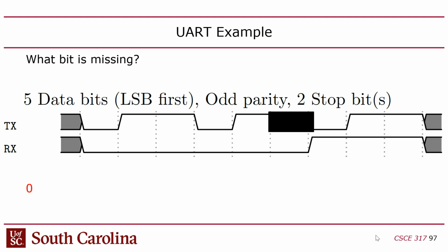Yeah, I always find that confusing too. The parity bit is not intended to be a signal in and of itself telling you whether it's even or odd. It's meant to pad out the bits to make the total number of 1 bits even or odd, right? It's meant to correct the number of 1 bits. But if you think of it as a separate flag, then you could just reverse the logic and say that odd parity is 1 when there's an even number, right? But to me, that's even more confusing.